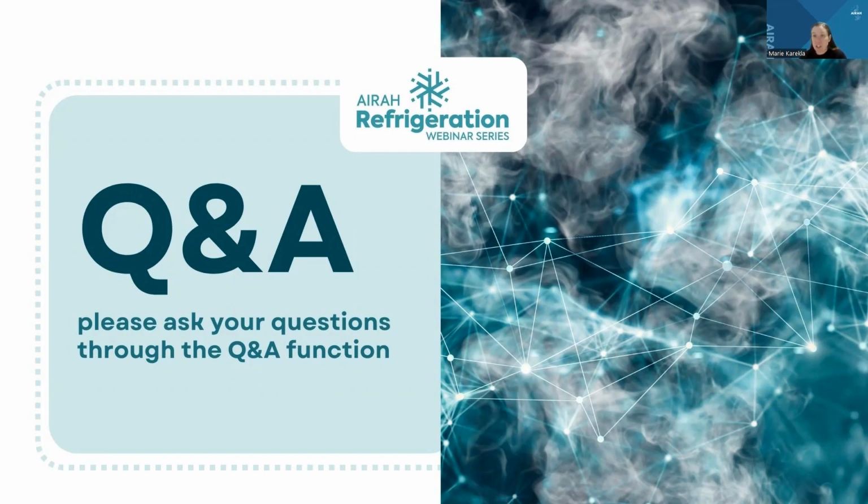That's okay. So Jason is asking, do you recommend air curtains in front of freezers or cold rooms to minimize air interchange? I mean, it will help, and also, I said, rapid roll doors, and again, depending how critical it is, and so on. Another way is to use chemical dehumidification to minimize frosting on evaporators inside a freezer. And also the design of the empty room as well. Getting rid of the moisture outside the freezer.